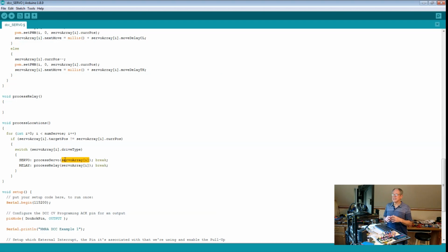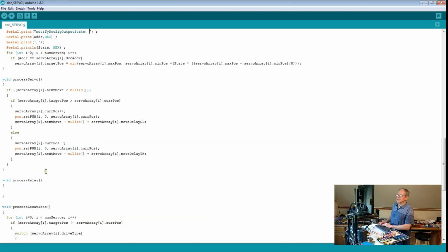The other possibility, I think, is more elegant. Instead of sending a copy, we send a pointer to that data. So the way we do that is we give as a variable, and we need to define that here anyway. That would be my servo, and we call it this servo. So this would be the static definition, and now we make it the dynamic definition. So a pointer operation by simply putting an asterisk in here.